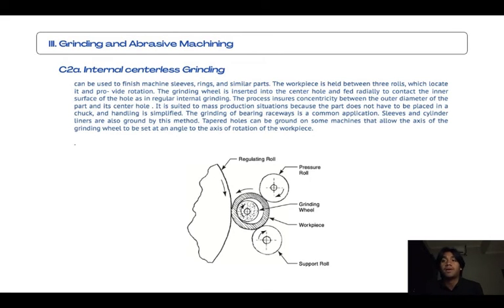Weldments, castings, and forgings are ground on these machines, and these parts usually have somewhat liberal tolerance for dimension and surface finish. However, vertical spindle machines have the capability of producing the fine finishes and close tolerances typical of toolroom work.